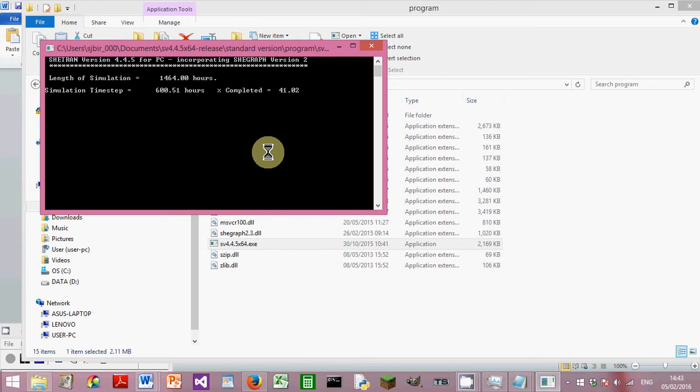The third way of doing it is very, very similar, but instead of copying those water tables, you need to copy the heads in that VSI file and change the 2 to a 3 in the VSD file. I'll just show you how to do that.